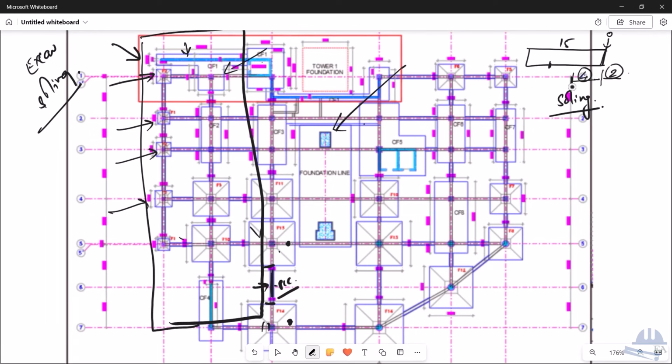So this is how you have to show the relationship in MS Project. Though at site, you can cut a box, do the soling, and also do the excavation at the same time. But this is not logical, or else you have to increase the number of days for the soling work, and that might not be realistic, because soling doesn't take more than 6 days, right?